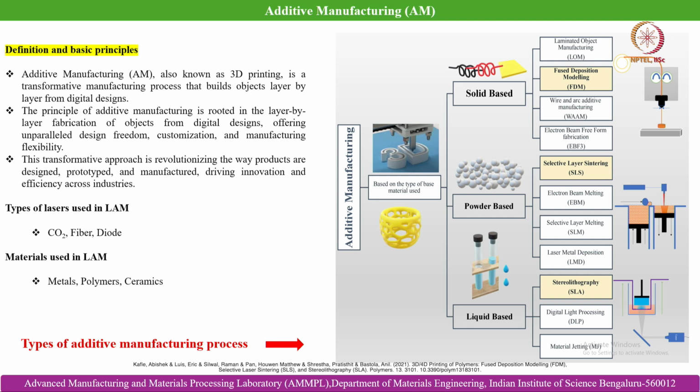You can understand from this image, this is an example of laser powder bed fusion. You can see over here, basically the recoater distributes the powder layer on top of the last build, and then the laser cures the preferential region, thereby in a layer by layer fashion, first layer, second layer, third layer, likewise we